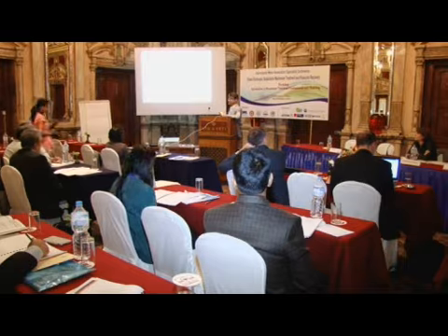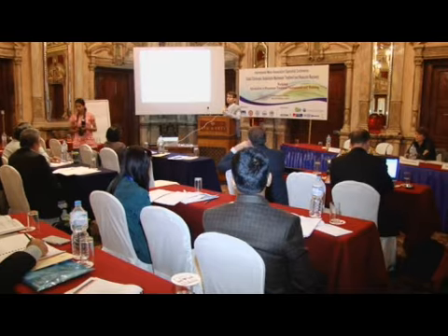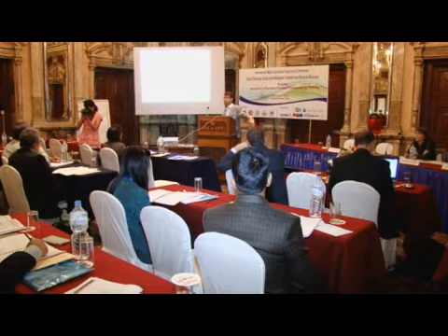We can roughly assume, if we put it on a carbon yield, half the biomass, apply a couple of factors on this, you end up with the fact that the BOD5 is a portion of the ultimate BOD. If you have the bottle, you put it there, and you just leave it, it keeps on consuming oxygen. We can assume it's more or less constant, although of course the wastewater itself, the quantity and the quality, the levels of organics, will go up and down.